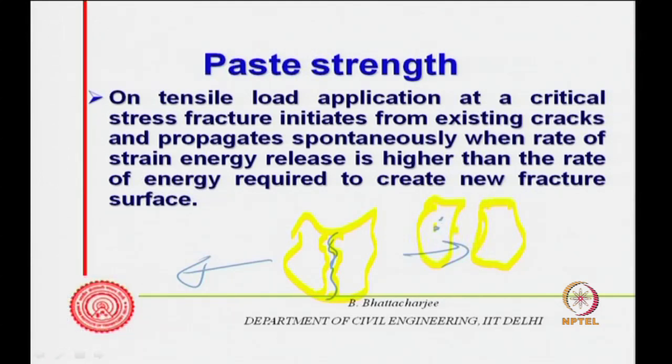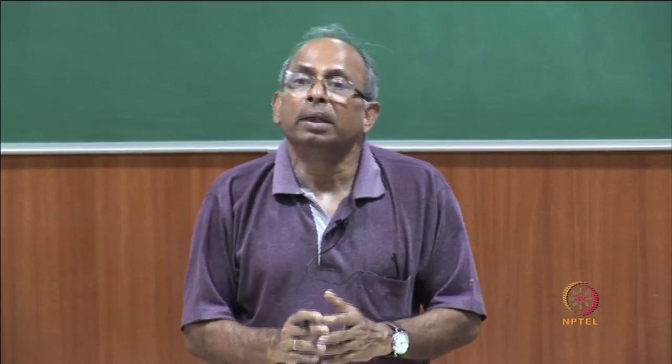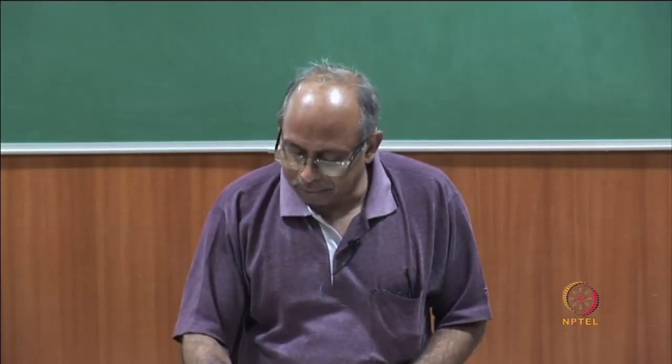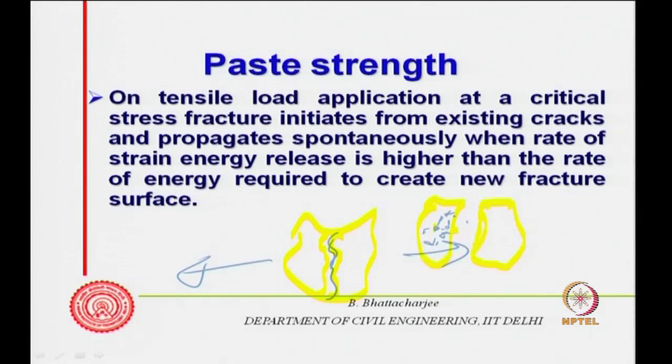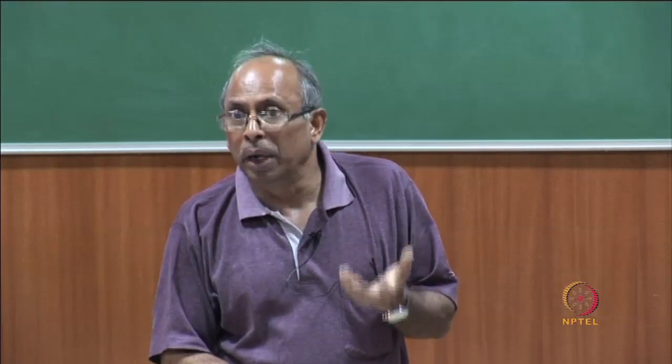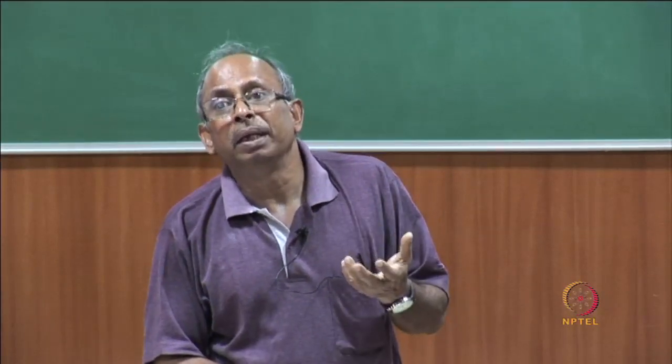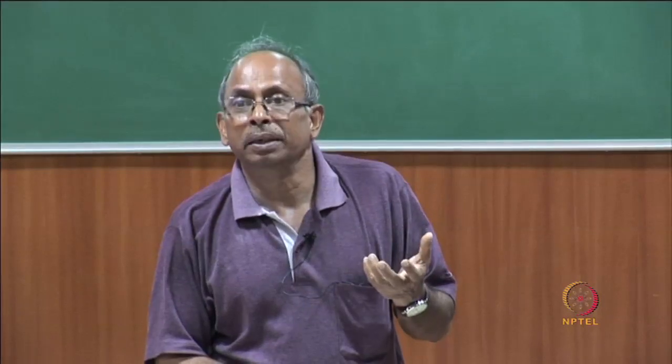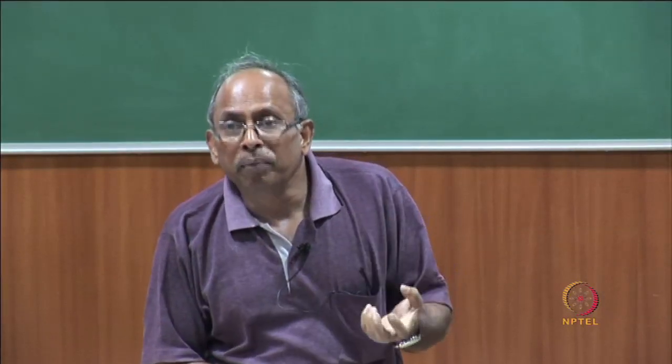will be pulled; it will be interacting with materials along all directions. At the surface, it will have cohesive forces, where the other particles on the solid side will pull, whereas here there is no such material. So, there is a kind of surface energy existing at the surface, and this occurs at any interface. So, since there is a surface energy at the surface, to create a new surface you must provide that surface energy. And where does this energy come from?